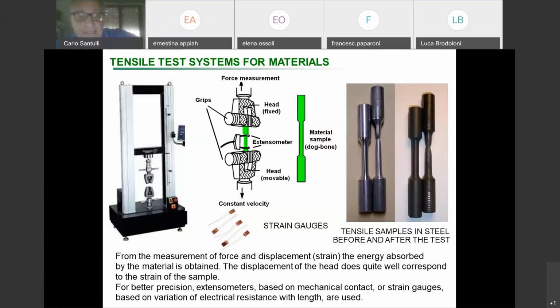But in other cases you are not able to measure by the scale, because possibly it doesn't stay straight, and also the elongation is not constant. So you may have further systems which give you a more accurate measurement, like the extensometer, which is a kind of two rings put at different places that give you the difference time by time, second by second, I would say.